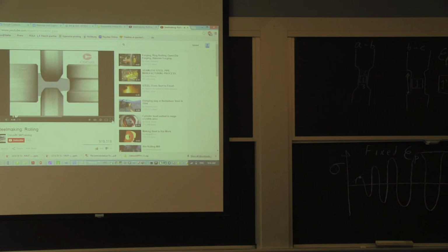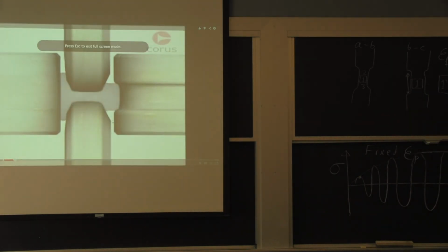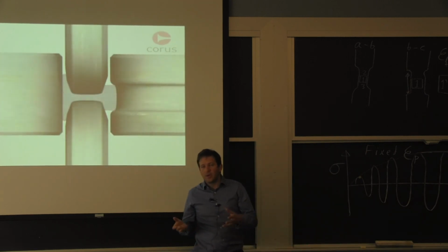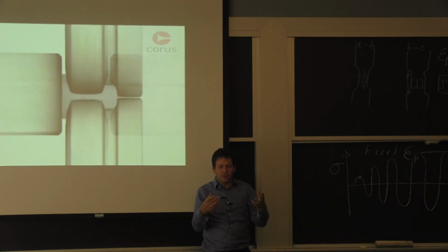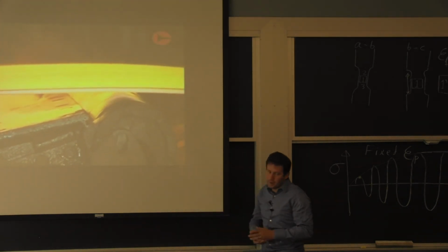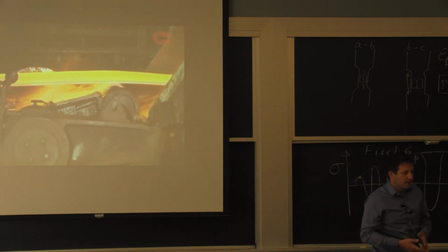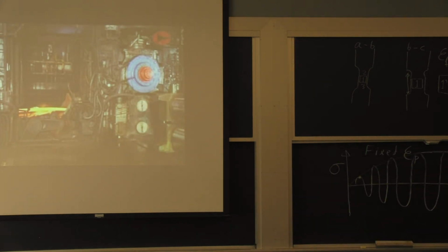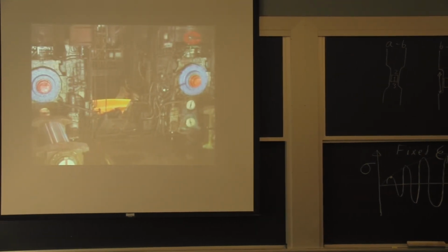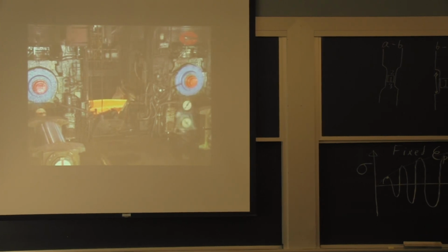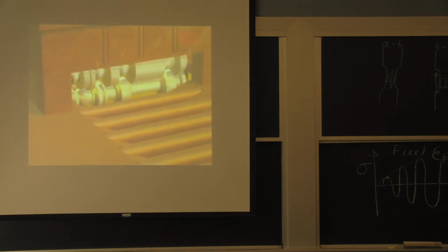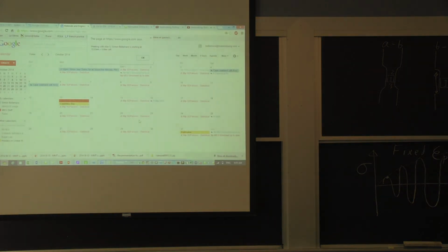The rolling operation, which is pretty much where we're going here in terms of being at temperature, is typically done subsequently. You would think you would cast and then try to feed the billet into this process, but most of the time it's stored temporarily, and then they go on to the high temperature process. Because of the amount of deformation you generate, typically you don't have to heat up the material as it goes through these processes. You're in the shop, you have a lot of radiation heat, you lose heat, but the plastic deformation, all this multiplication of dislocations, generates heat as well.